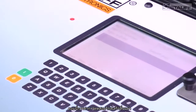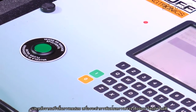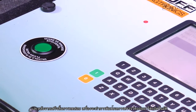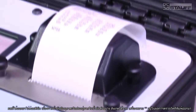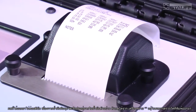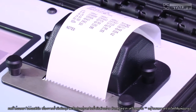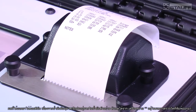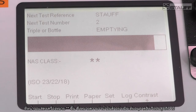So the sampling bar is almost complete, and as soon as the test is finished, the printer will print the result. Okay, so we have the result, but it's not a very good result. We only have 2 stars. This means that the oil sample is very dirty, so it's outside the limit. So if you see a star like this, it means that the oil sample is very badly contaminated. So it's outside the limits of the particle counter.